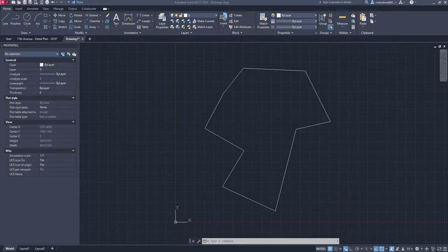Now, you landscape architecture students in the class are going to find this next tool particularly useful because it's super valuable for inputting surface areas into a closed shape. The tool I'm talking about is the Hatch tool. Hatches are super valuable tools in AutoCAD that let you fill an area with a pattern. Provided these lines here are forming a closed shape, you'll be able to input a hatch into that. And here's how it's done.